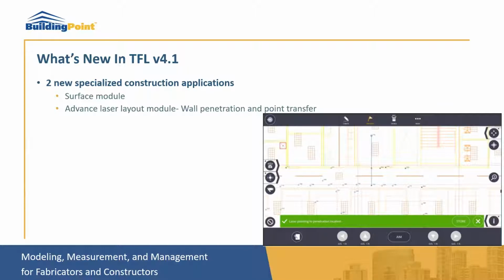So instead of drilling everywhere or making a big hole in the wall, you can select 2 points that will be separated by that wall. Just turn your instrument to aim at this wall and then click on the aim button. The laser will turn on and your total station will aim where the intersection of this line with the wall, the vertical plane, is happening. So you just need them to drill a hole at this area.